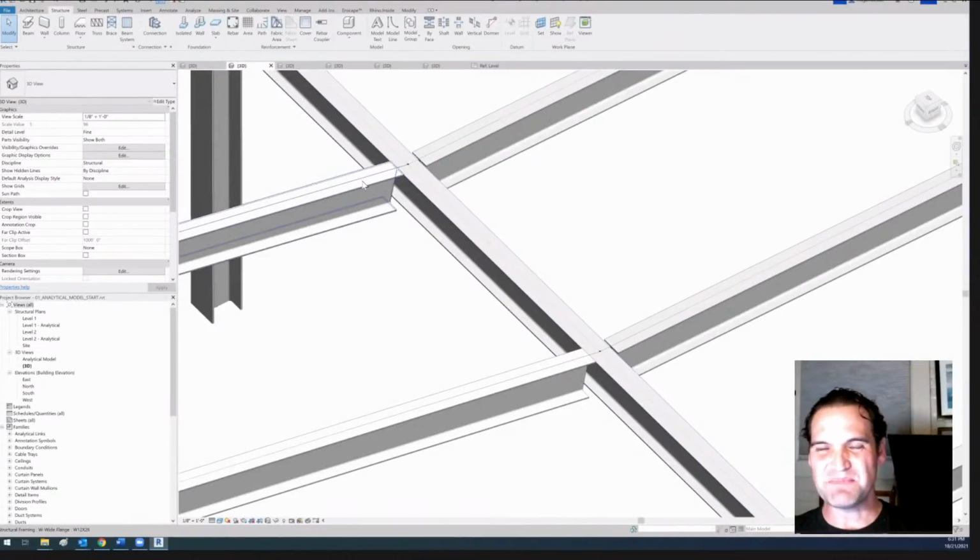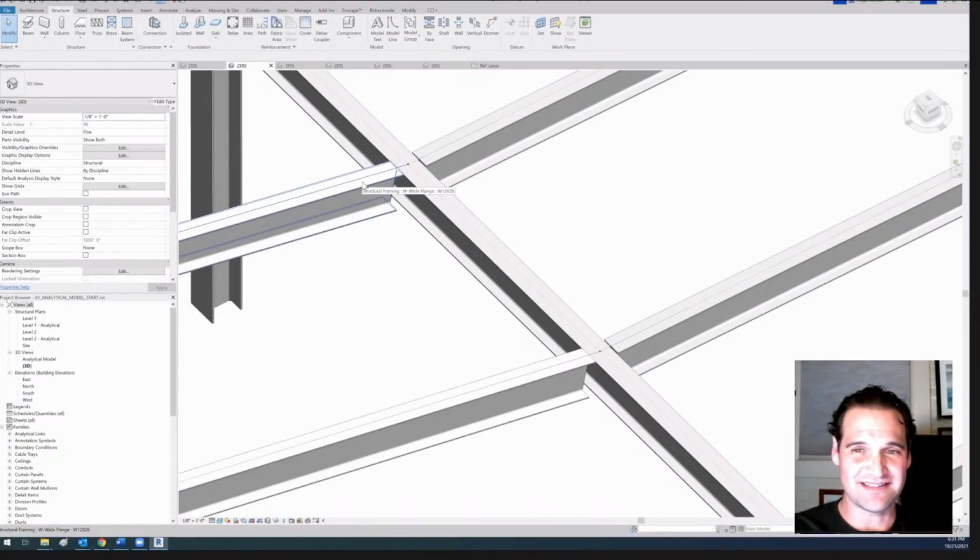This was if the beam is natively in your file. If it's through a link file, well, you can't edit a linked file anyway. You can only look, don't touch on a linked file. You would just have all those limitations. At this point, if you have a hard rule about not modifying structure in a linked model, you could turn on analytical, see there's an issue, then talk with the structural engineer or the author of that 3D structural model and show them how to make the adjustment, like I just showed you with the analytical, just putting in the beam, and they may appreciate that.